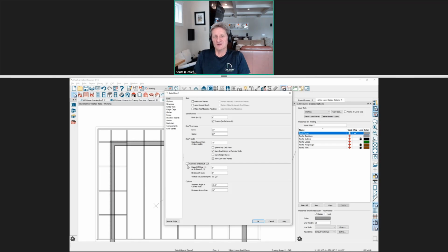So I guess, to be fair, your question is why do we have both of those? Why can't we just use one? Well, with trusses, since they don't have a bird's mouth cut, I always check that off and use the roof height raise lower for my truss. But you didn't do it that way, and I'm wondering if there's a good reason to use one or the other.